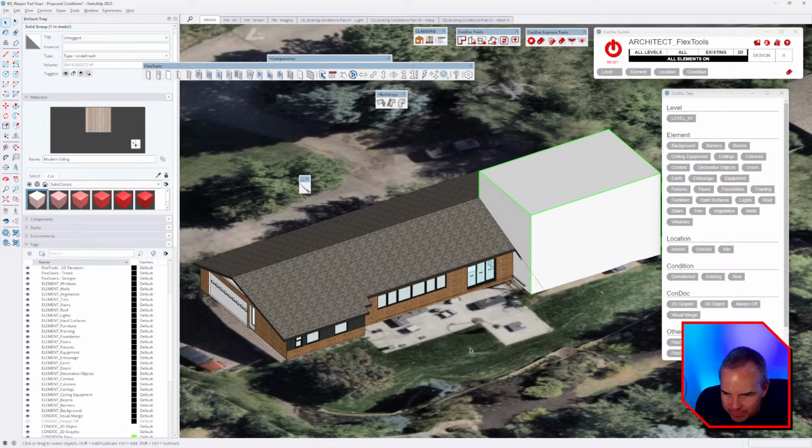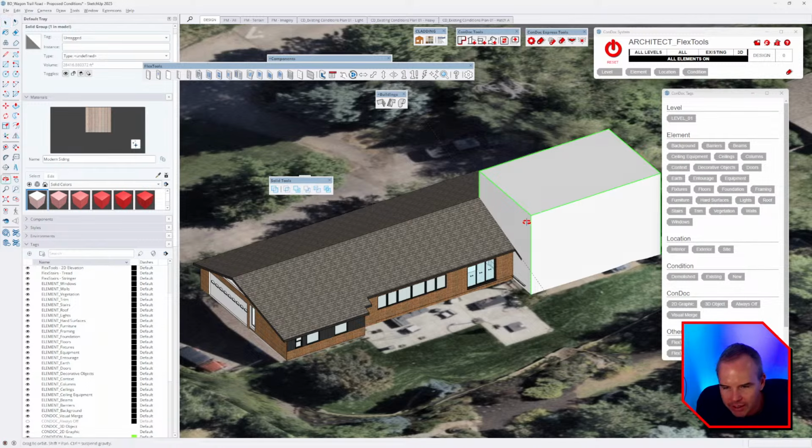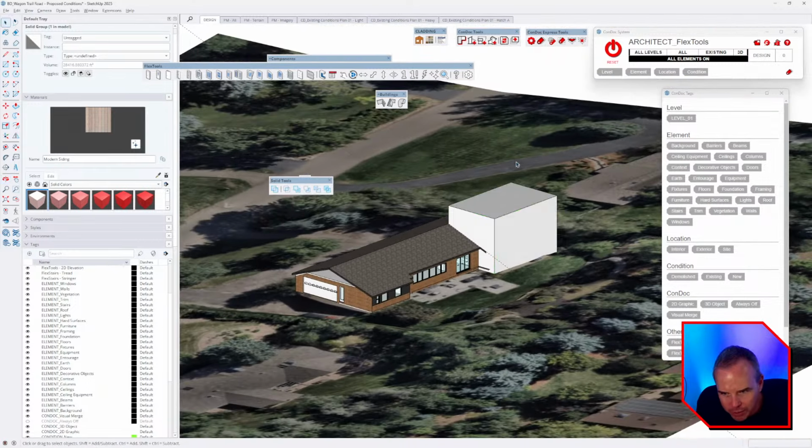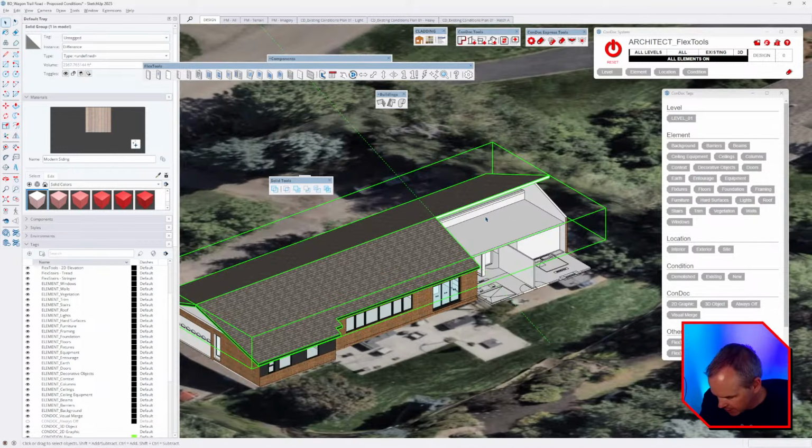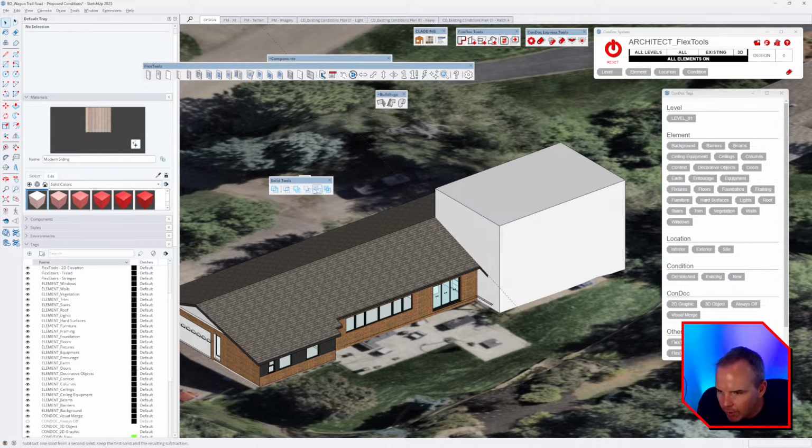Let's see. Solid tools. We do this to that. So we want subtract. And I think the clearest way to teach these tools is to have no selection, although you could pre-select it. And we're going to subtract this from that, like that. Oh, but you know what? I don't want it to be a subtract. I want all the pieces to remain and only keep their overlapping. I want to split this and that. All right, so now I can delete this.